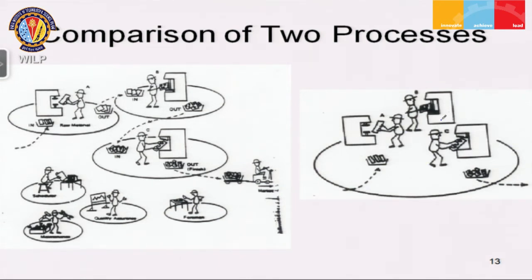The quality is a much simpler task, simply because anytime there is a problem with a particular part, so let's say there is a problem in one particular piece that the first operator works on and hands over to operator B, immediately operator B will say, I've got a problem with this part, hold your horses, do not work on the next piece until we figure out where the problem is, usually some sort of an issue with the setting on the machine, and so you don't have an entire batch of bad parts produced, and you get immediate feedback when there is a quality issue.